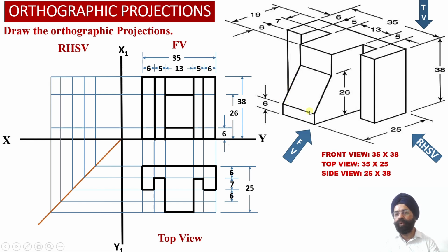So this rectangular projection will be viewed as an apparent shape projection in the top view. We can check this inclined surface has been projected as an apparent shape projection into the top view. It's a very big surface. Corresponding to this relatively bigger inclined surface, we have obtained a foreshortened apparent shape, a rectangular projection in the top view.